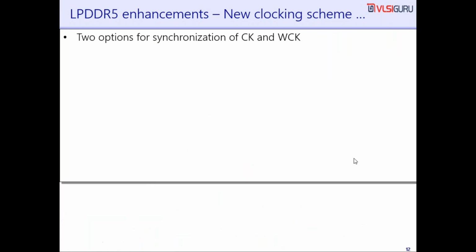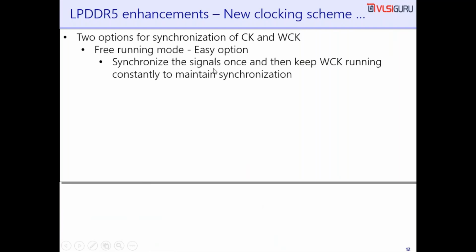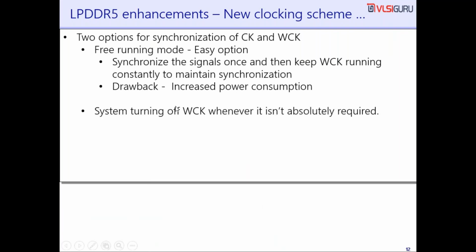Two options for synchronization of the clock and WCK. One is free running mode. That is the easy option. Synchronize the signals once and then keep WCK running constantly to maintain the synchronization. The drawback is what? It comes with increased power consumption.